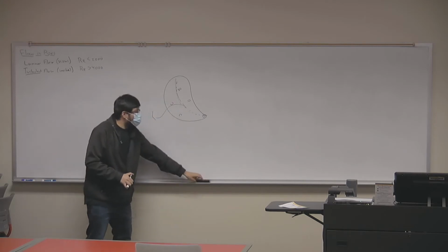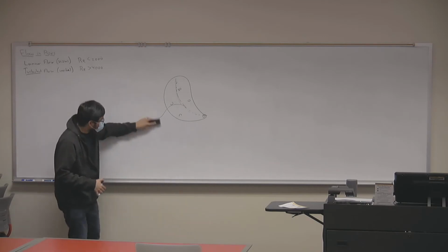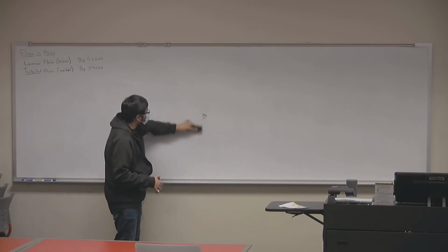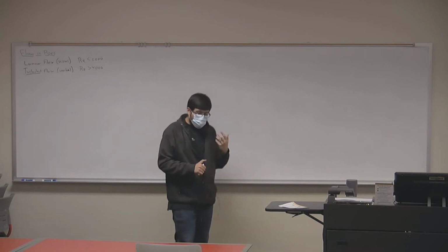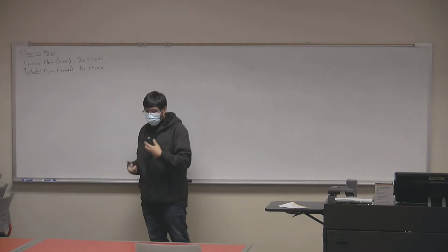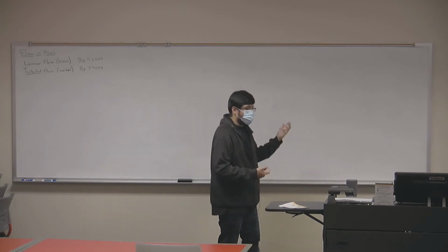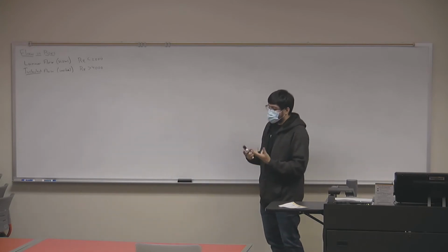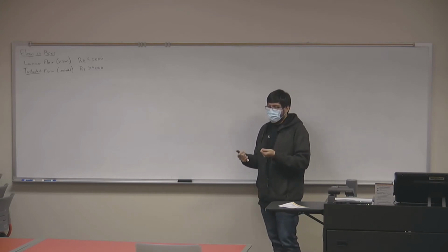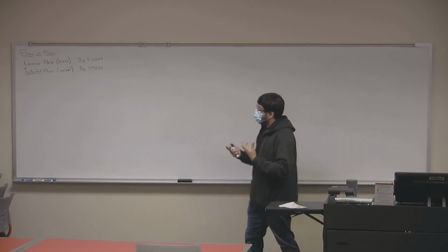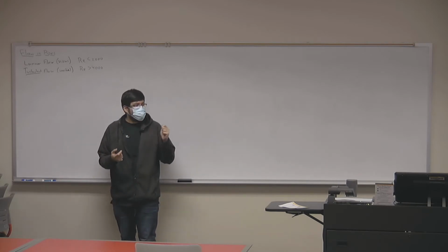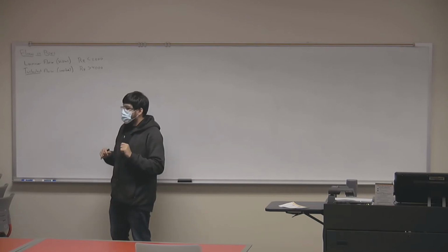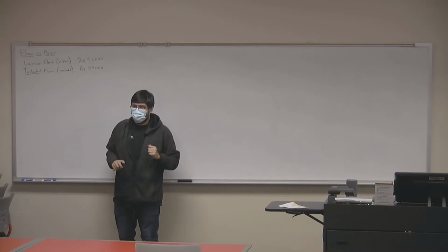And that's the type of analysis that we're going to do in this class. Because this is an introductory class, our analysis will look at averaged values. We can average our values such as our velocity field, our pressure field, even our density fields for compressible flows. We can average them over time. We can average them over a depth. When I say we're averaging our values, it means we can't really calculate every single velocity of a fluid particle with precision, but we can at least find a trend of where the particles are moving.